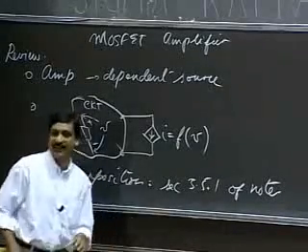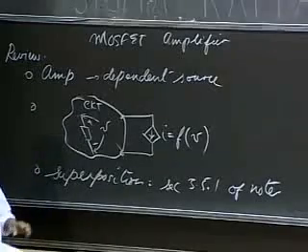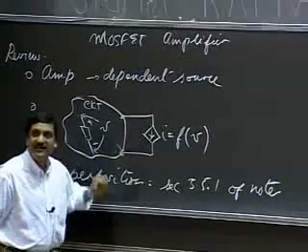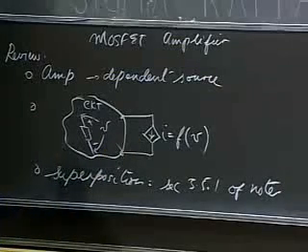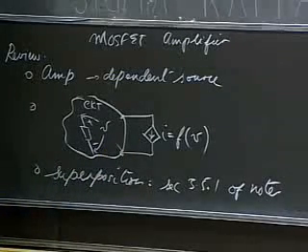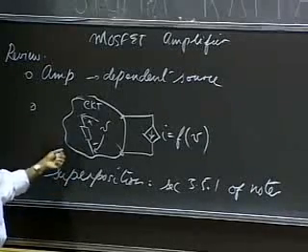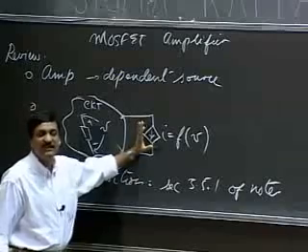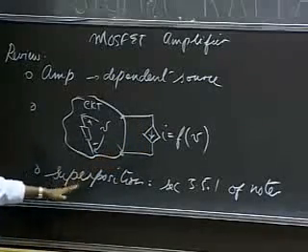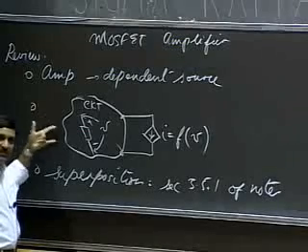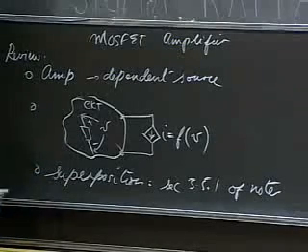So the approach is very simple, actually. The approach is, for the purpose of superposition, to not treat your dependent sources as sources that you turn on and turn off. Okay? So what you do is, when you do superposition with dependent sources, simply leave all your dependent sources in the circuit. Just leave them in there and turn on and off only your independent sources. Okay?